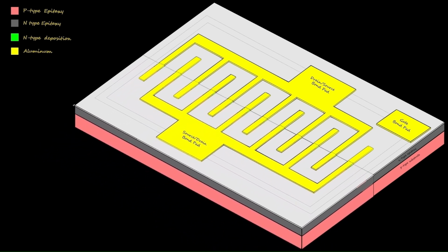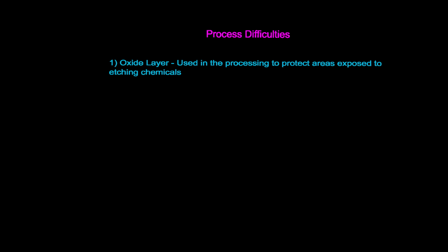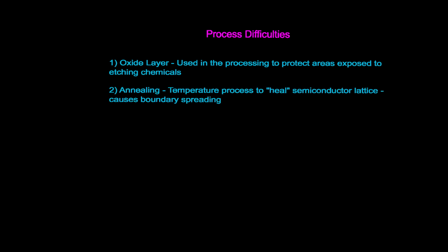Actual semiconductor processes are more involved than what has been presented here. There are more steps in the manufacturing process because the masking procedure uses an oxide layer that is removed and added in successive steps as the microstructures are created. Also, after ion implantation, the wafer must be annealed to allow the atoms to settle back into the crystal structure. Each heating process causes atoms at all the boundaries to diffuse slightly.